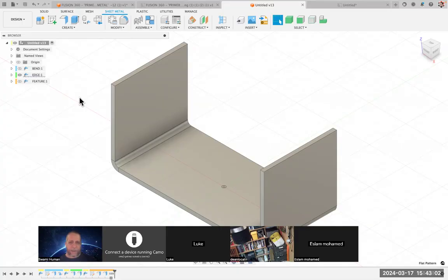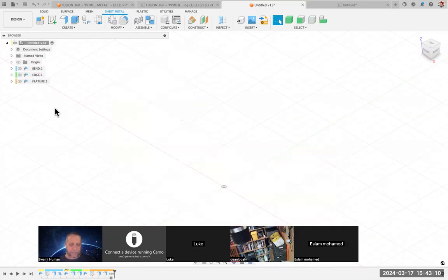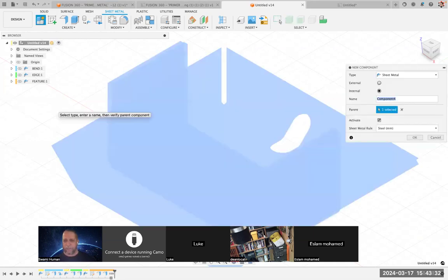And we are going to make a new component. We're still in the sheet metal. We're at the top. We're going to hide that guy and save before I do my next major action. All right. I give everybody a moment to get up to the same place. We should be looking at previous things turned off. And we're at the top level, root level active. And we're going to Shift C. And I'm going to hit tab to go up to the name. And this is going to be contour, C-O-N-T-O-U-R.